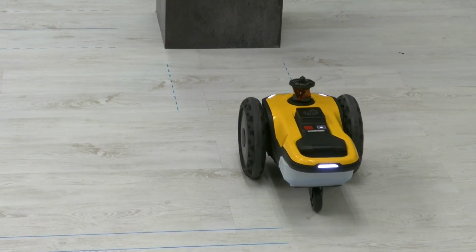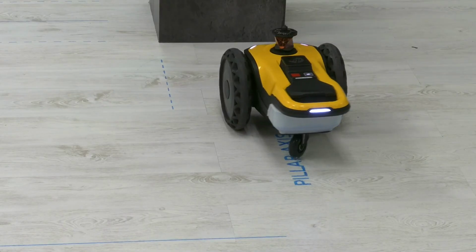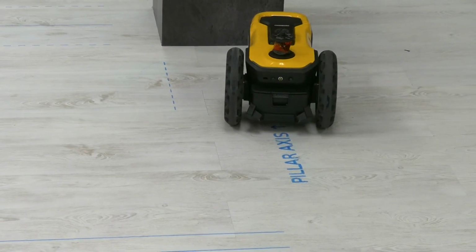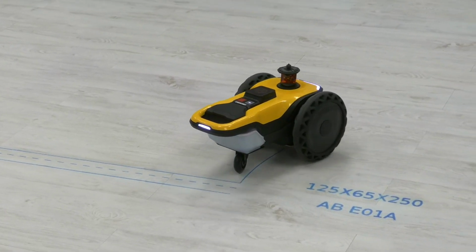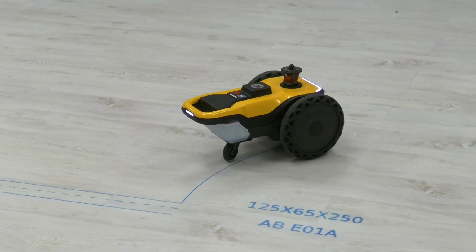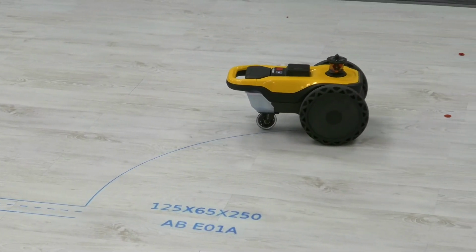Wheels are big enough to overcome floor roughness and obstacles about 1 inch thick. Additionally, there's enough clearance between the printhead and the floor to allow the robot to keep printing even when tilted, as it will compensate the firing of the ink accordingly to get optimal results. Regarding the battery, HP SitePrint comes with 2 batteries that last for about 4 hours, so combining both will get you through the whole shift.